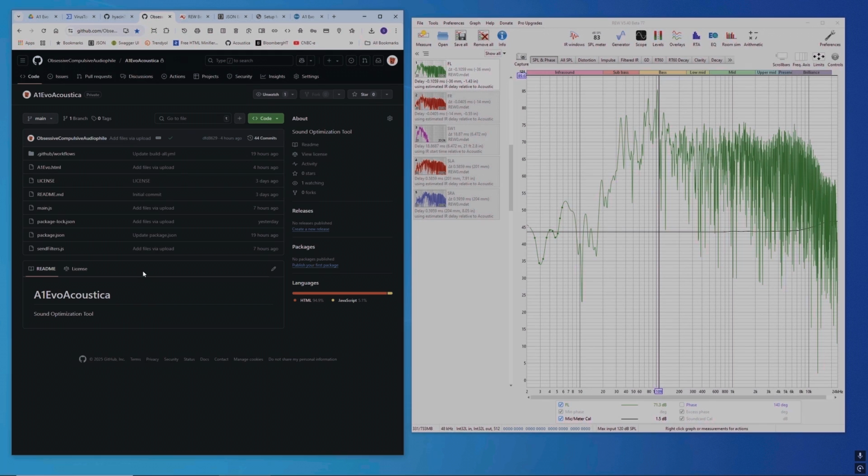It needs a measurement tool. We are now aware that we can use Audyssey measurement tool, manipulate it to actually even individually measure subs. Many of these receivers can do directional bass. By the way, if you're measuring manually and you have more than one sub, put your amplifier to directional bass mode during measurement, so you can measure individually each sub. Otherwise you have to swap RCA cables during measurements, because you have to have individual measurements if you have multiple subwoofers. That's important. But we know that we can even override that and measure subs individually using Audyssey measurements, but